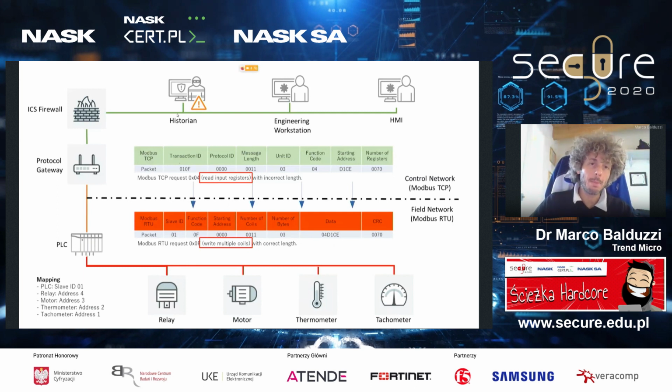So this read request bypasses the ICS firewall that we assume a conscious and intelligent and smart OT engineer has installed to prevent malicious packets, like write packets, for example, where you set values on the field network to be transferred down to the PLC. The ICS firewall normally allows read requests, where you read data from sensors on the production to monitor the production, but does not allow, for example, a write request, where you reconfigure a motor, a relay, or something like this.